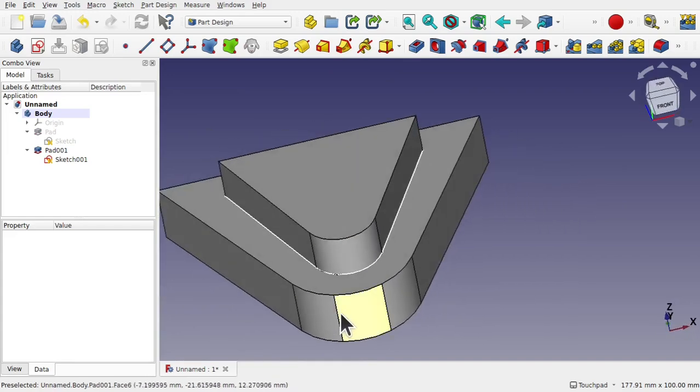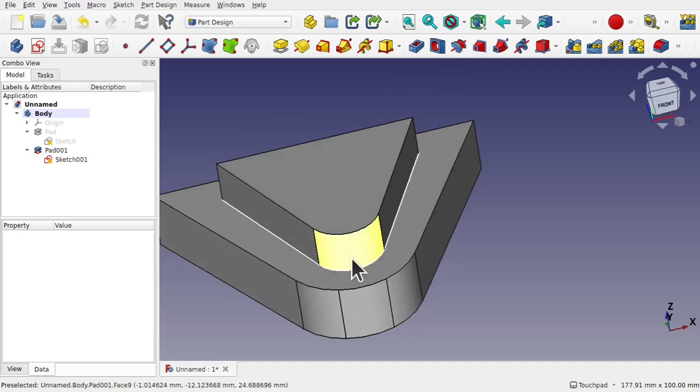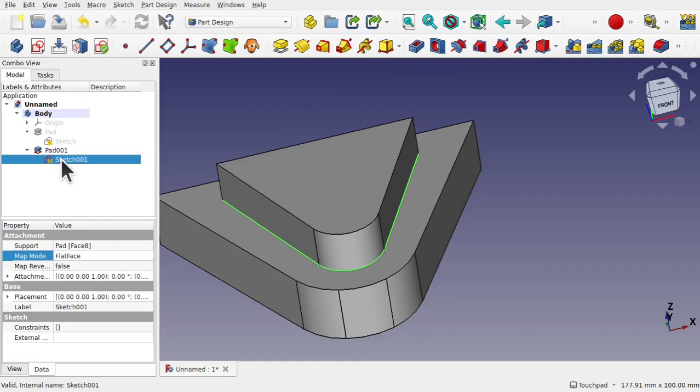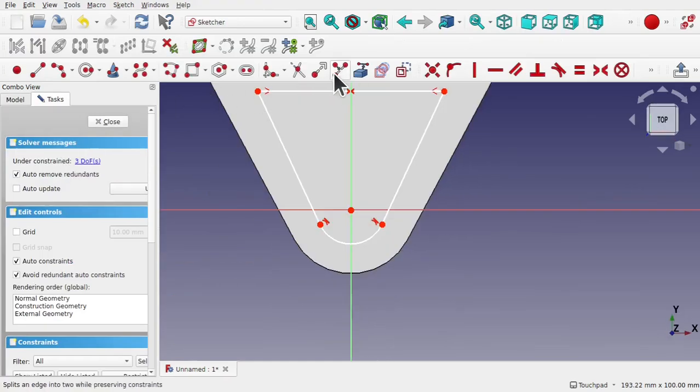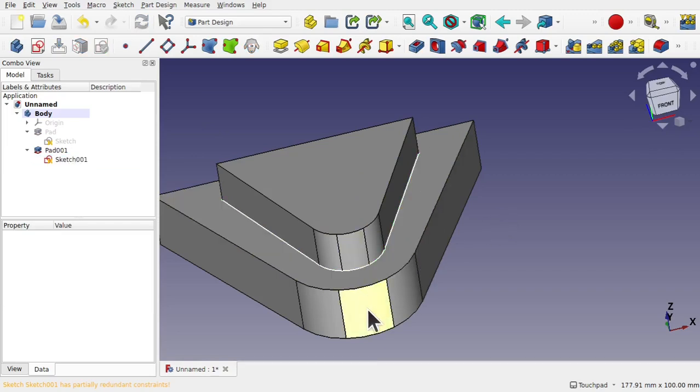I'm going to create another split like this one on this side. We could use this if we wanted just to loft between these two faces, but I'm going to do the same on this side. We've got no operations in front of it, so we're going to be OK. Let's double click that and add the split. And we just split these two and take this point, and the vertical axis, and just use symmetry across those. Hit close. We now got these two faces.